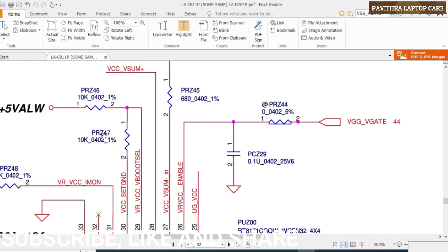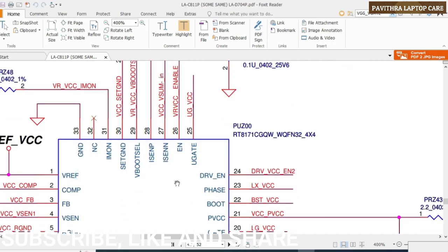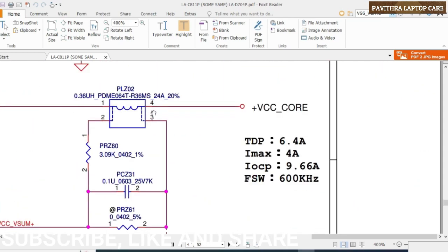It may be because this resistor is faulty, or maybe because the IC is faulty. It generates up to one particular frequency. If the frequency is increased, then this particular coil will get heat. Understood? Sometimes you feel it is a display problem, but the thing is you will get more heat on that particular coil. That is the reason.